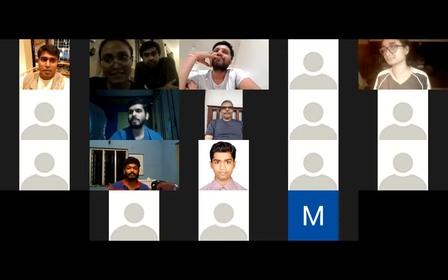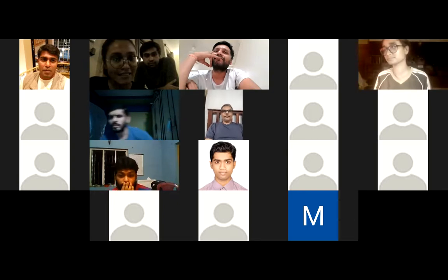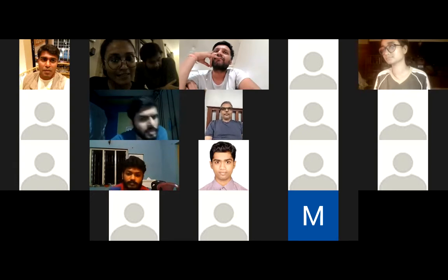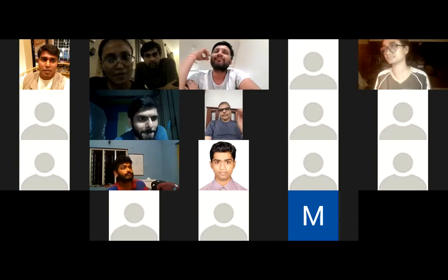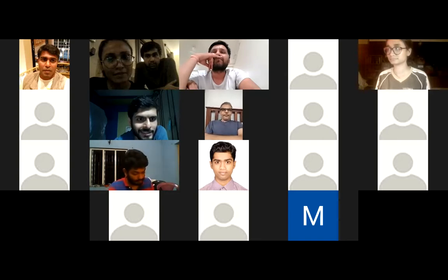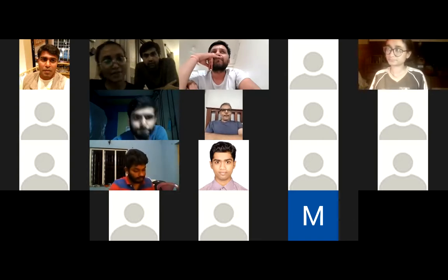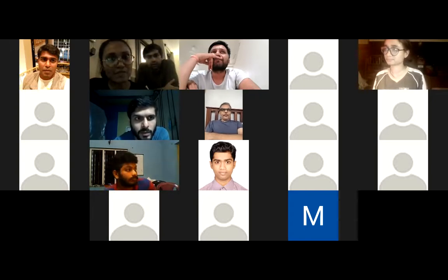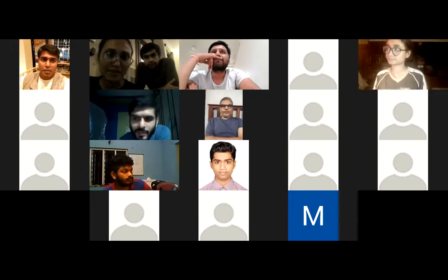Richa, I would like to share one thing from my friend in Chennai. He's a chemical engineer. When I shared all my requirements, he told me to utilize zeolite 5A. Apparently it's a better zeolite, in my opinion, right? Am I right or wrong on that? No, that's right, equivalent to 13X, and better in some places. It depends again. It's a function of compressor and zeolite, at the end of the day.